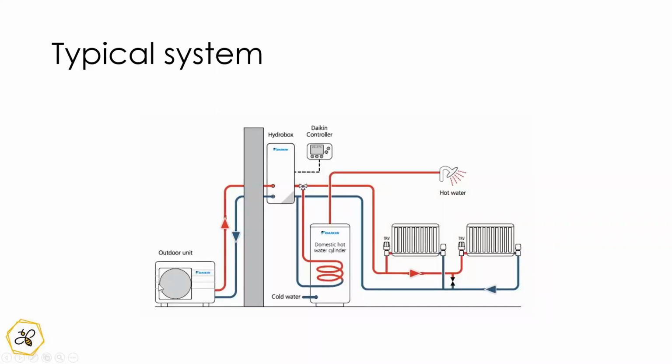You're doing most of your heat pump work out here, taking heat in, and then you are sending that heat either to your radiators or through to your hot water system, and then you're drawing off your water when you need it. And you won't be able to do a combi boiler, because that's just not feasible with these temperatures.